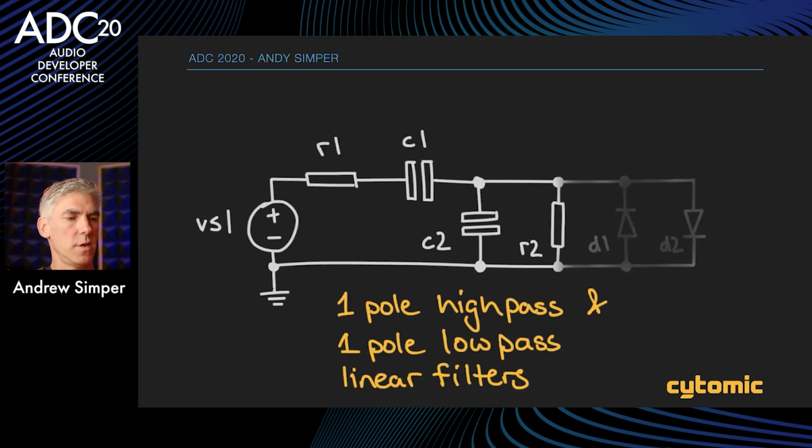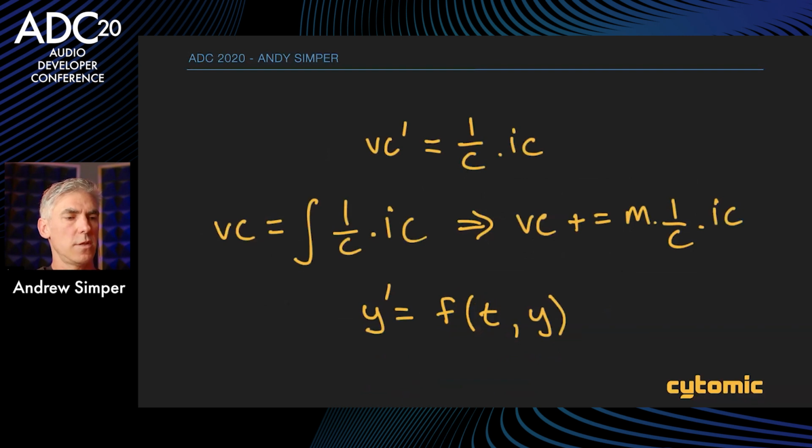We've covered implicit nonlinearities. Now let's do memory filters, in other words. So this, again, it starts, I'm sorry that I can't write it in a more pictorial way, but I will soon. A capacitor is something which integrates current. So you give it some current and it adds it up, plus equals the current. Or another way to write that is that the derivative of the voltage of the capacitor is the current. So they're basically the same thing. I think this is probably a bit more computer friendly. The voltage plus equals the current.